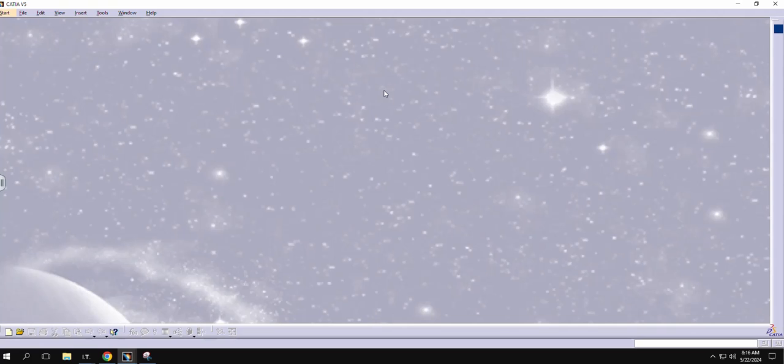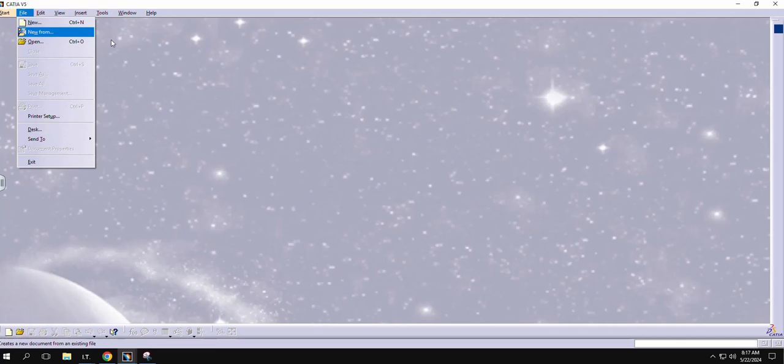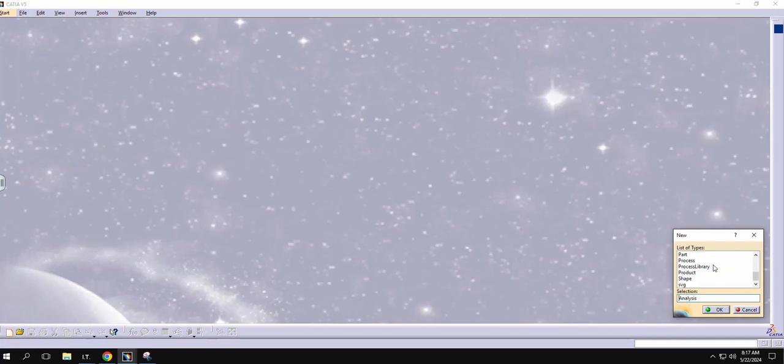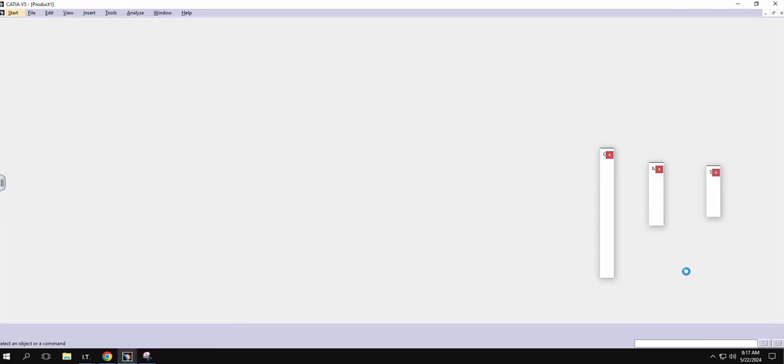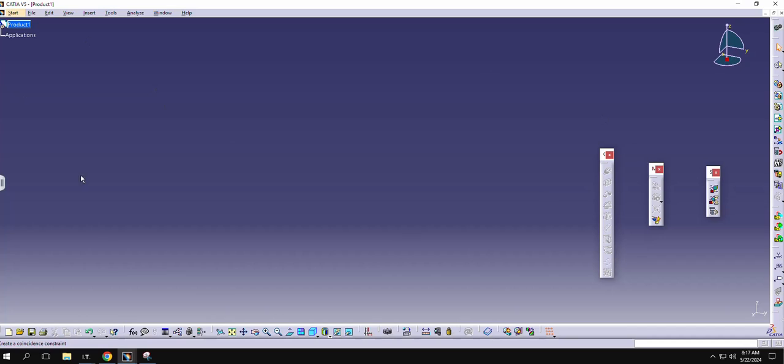In this video I will show you how to make a design assembly. So let's get started. First of all we will click on file, click on new, and instead of a part this time we'll go on product, double click on it. So our product window will open up.